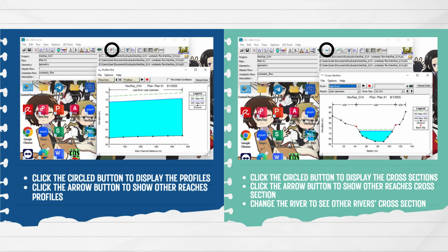And if you want to see other profile, you need to click the arrow button and it will show other reaches profile. Lastly, you need to click the button of cross section to display other cross section. So if you want to see other reaches cross section, you need to click at the arrow button. So lastly, you need to change the river to see other river cross section. For example, Lipis River, Lipis upstream and Lipis downstream, and Tempere River. That's all.